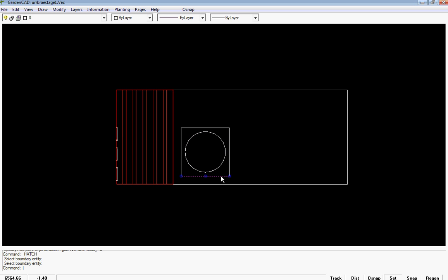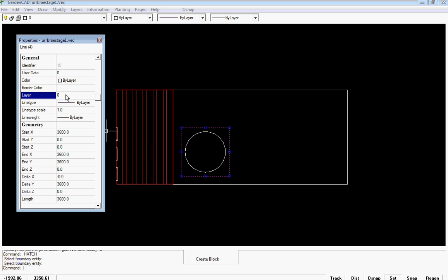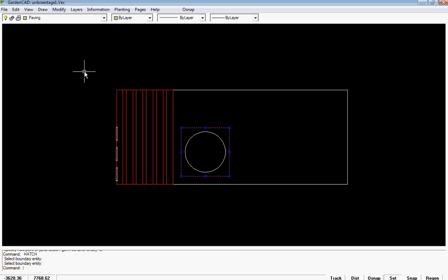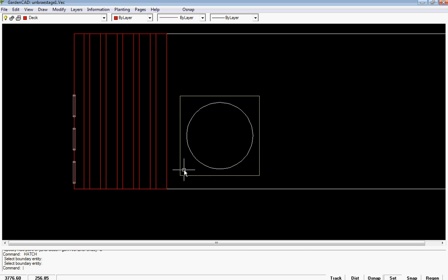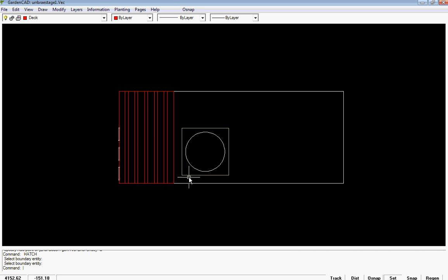This shape here, that one there and there, that's going to be right click, properties, and we move it to a paving layer, and its colour should change as we do it, and we get a faint change. So can you see we're setting up the layers so that we can put specific entities on specific layers. Our next stage, in fact, might be to create an irrigation layer and then to put our 600mm paving bricks over this area.